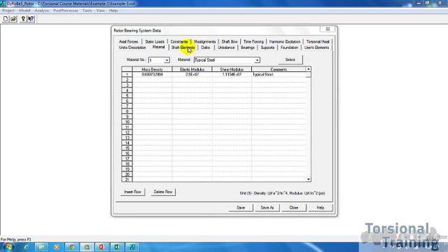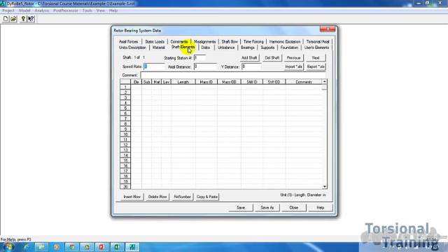And after selecting the material, go ahead and now click on shaft elements. And this here is the meat and potatoes of Dyrobes. This is where you build your rotor. Dyrobes follows a sort of a finite element approach. If you've had any experience modeling using ANSYS, then sort of think about what you do. You select your units, you select your materials, and then you do your pre-processing, build your model, and then you assign your elements. So we're sort of following the same basic approach.